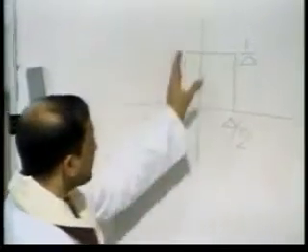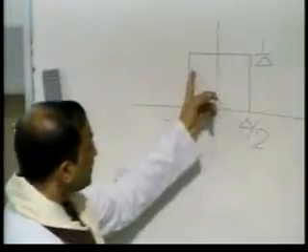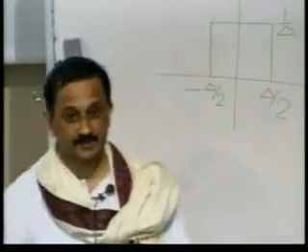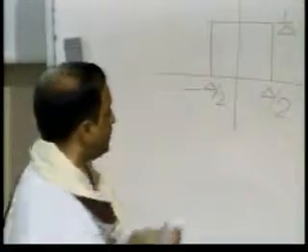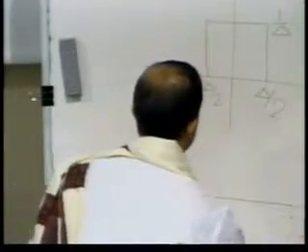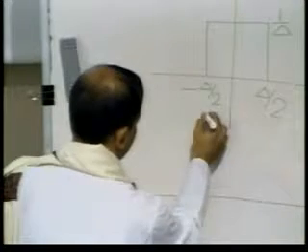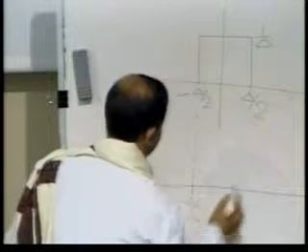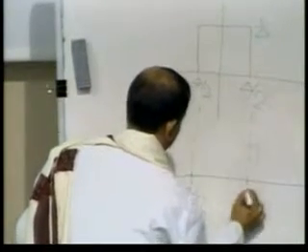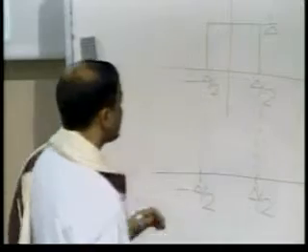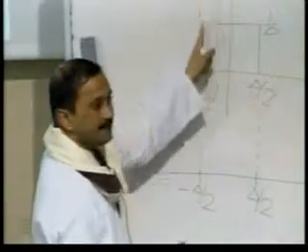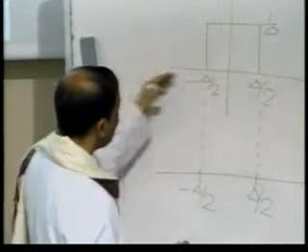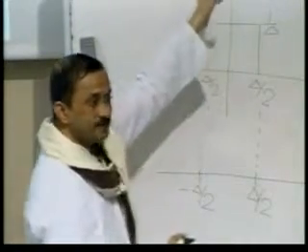So what kind of a derivative does this have? You see here, of course, the moment you have a discontinuity, we have agreed that the derivative must have impulses. So here we will have a situation like this. There is going to be a positive impulse, because the function is 0 up to this point and then suddenly rises to 1 by delta.